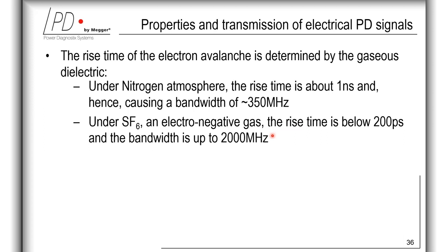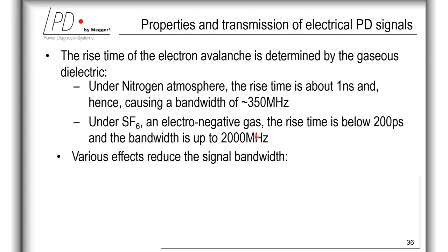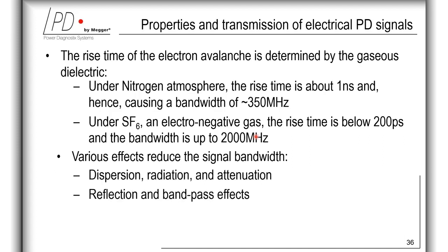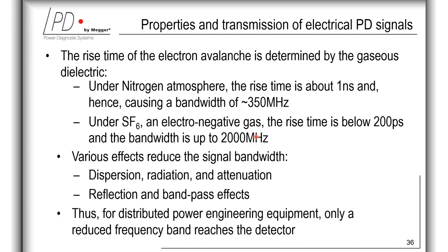However, whenever the test object becomes physically large, the influence of the internal and external leads has to be considered. This concerns effects such as attenuation, dispersion, and reflection. Likewise, the antenna effects: here we concern both radiation as well as reception, including cross-coupling.